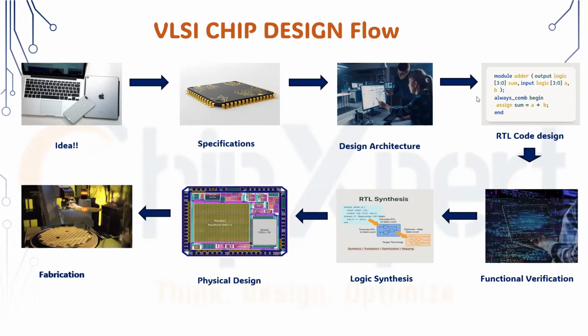We should not use as many gates as we want, right? So we have to trim them. Logically, the functionality has to work, and also the design has to be properly verified. This will be done at synthesis, and the functional team, like the design verification team, will verify this logic in a to-and-fro process.